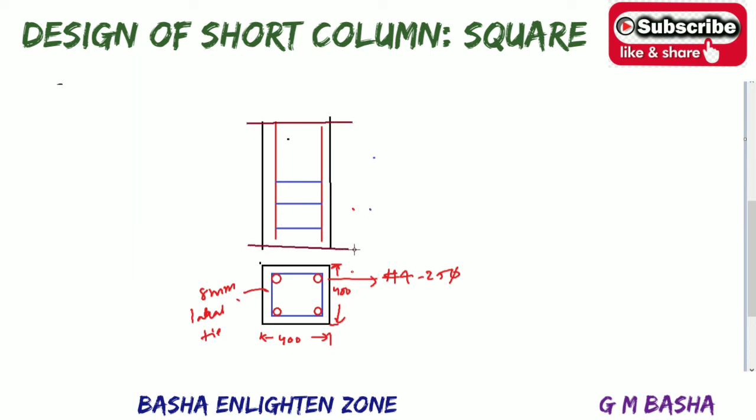So this is the continuation here. This is also restricted to 3.3 meters only. We are designing the column, so provide all the things in the required data. This is a longitudinal bar of 4 bars of 25 dia. After cutting the section, the elevation will be in this way. Here also it will be like this.